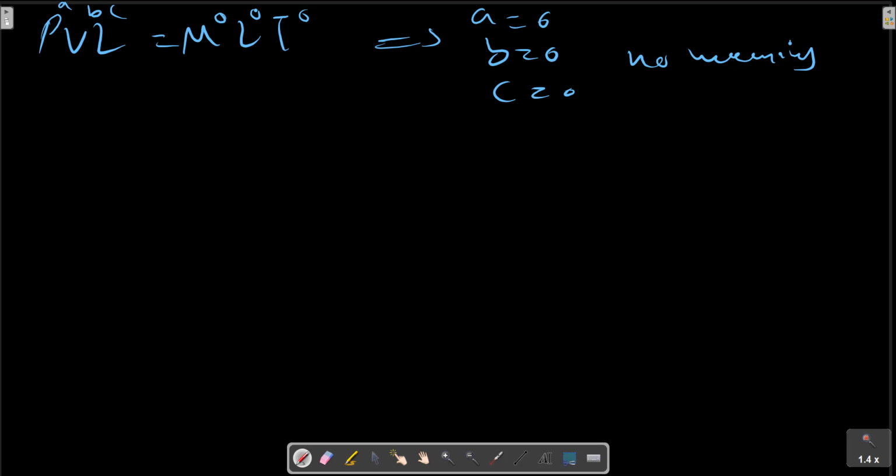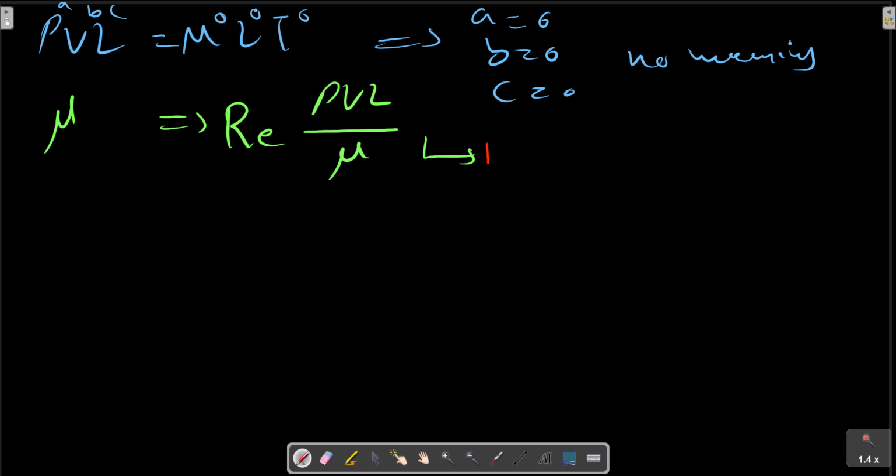So we should add the viscosity in the relation to the scaling group to obtain a dimensionless quantity, which in this case is the Reynolds number, rho V L on mu. It is a non-dimensional number. If we add F to the group, we form the force coefficient.